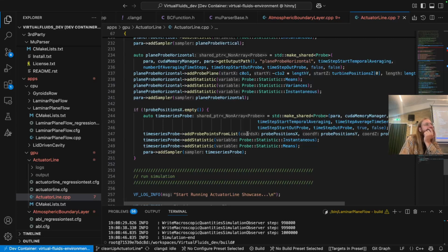So we have two nodes near the wall, before the boundary condition, on top of each other, and we expect this to be a log law. If you have the velocity at the second one, you can calculate the velocity at the first one and just apply a slip. Does this work? No. Because how do you set the velocity? You can set the equilibrium from the velocity, but that's not going to be good. You also need a viscosity to do that. No, I mean I do a velocity bounce back at the node near the wall, based on what I calculated from the log law.